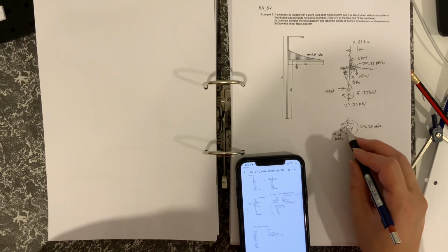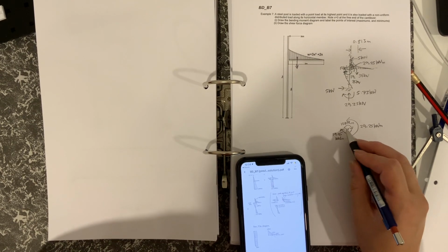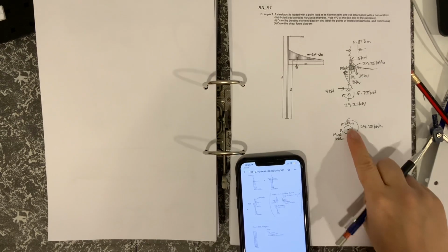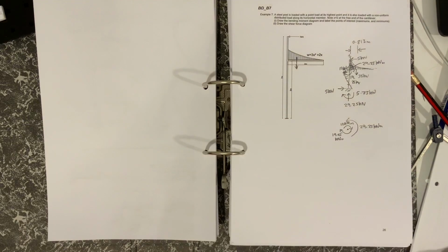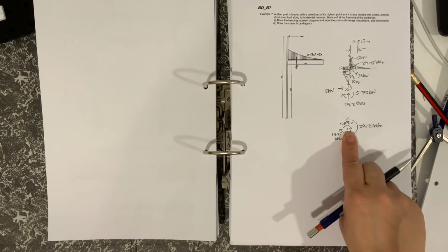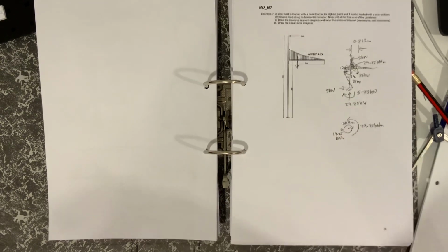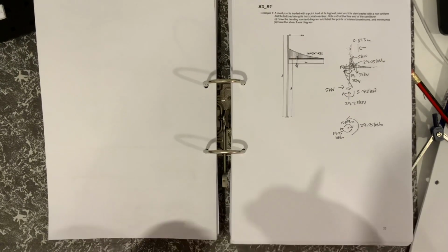That one plus that, these two are both in the same direction, that's in the opposite direction, so the net moment is 0. So that was a check you can do right at the end to make sure that you've done the calculation correctly.